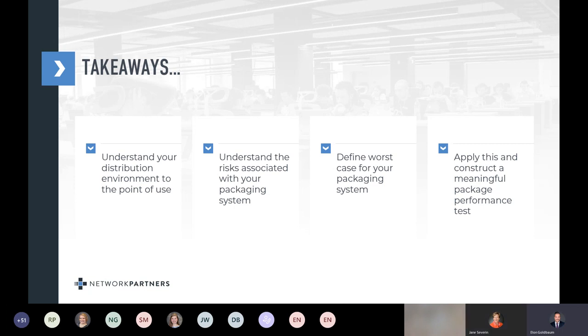Okay. Yeah, and I think as we all do, we get our sample sizes based on severities or the risk priority number from your FMEAs, your risk documentation. And that kind of dictates your sample size. The way I've done it in the past in many validations is 95% confidence, 95% reliability, which I believe equates to a sample size of 58. Usually we round up to 60 anyways. But what that would mean for attribute testing, because typically attribute testing is a sample size of 398 or 298 and 598, is a lot of resource commitment there.